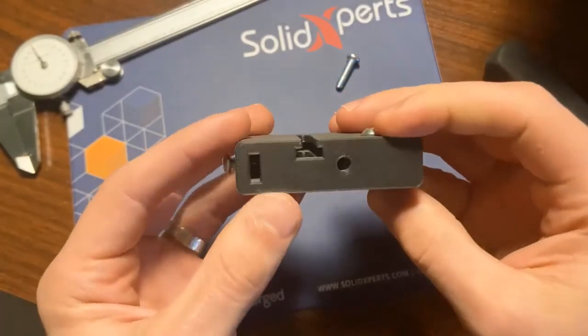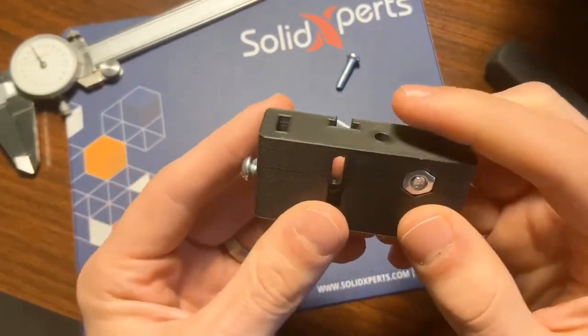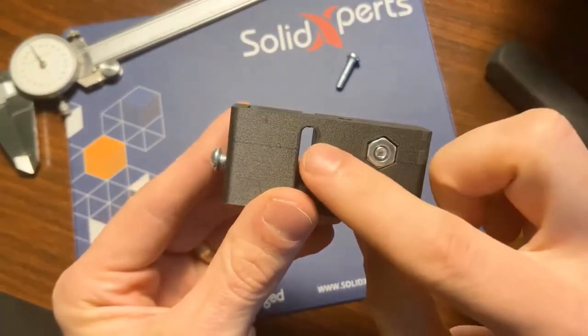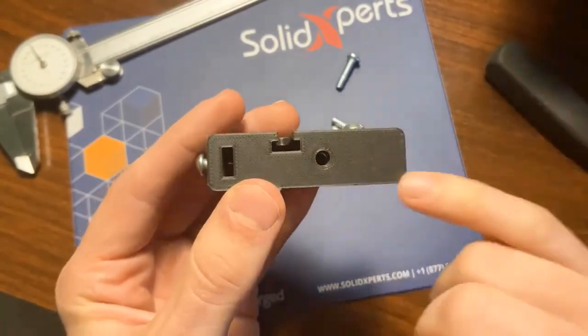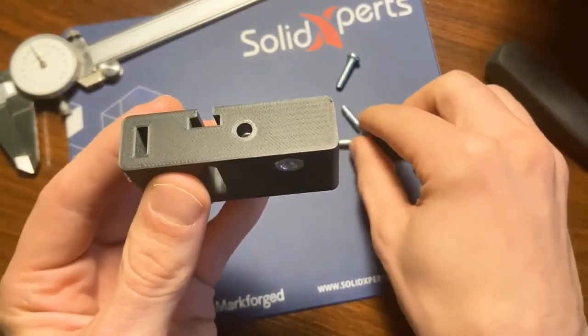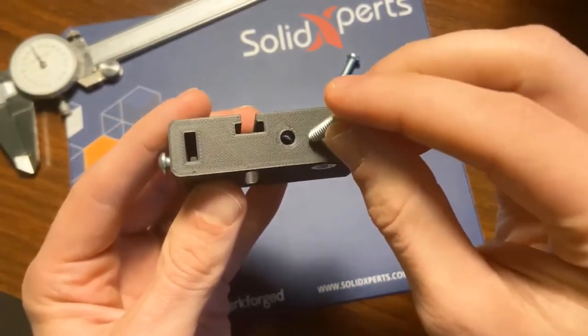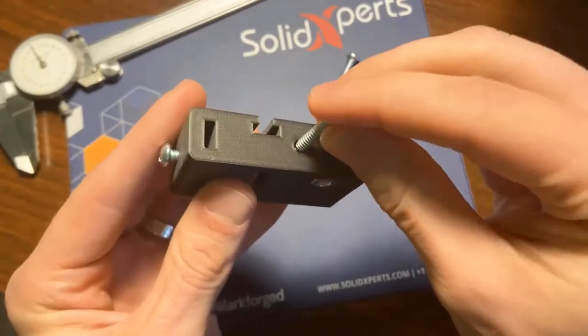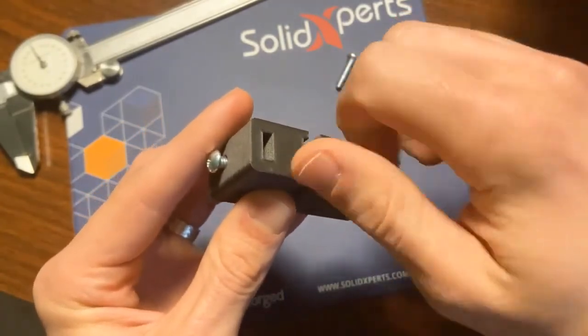There are also examples of the embedded fasteners. So there was a pause function. See a little bit of a line right there. There was a pause function where we inserted a nut, put a small spacer over it, and resumed printing. So in this case, there's a small nut in there. It's hidden, it's embedded. And again, we can add another fastener.